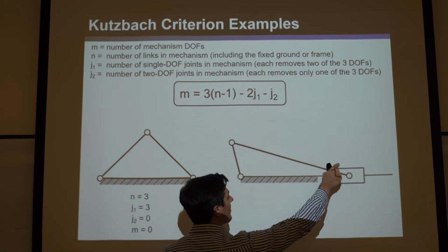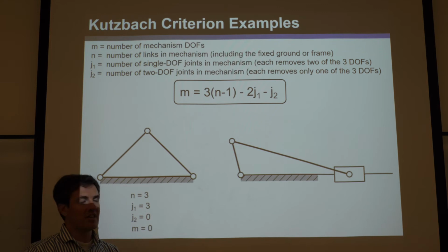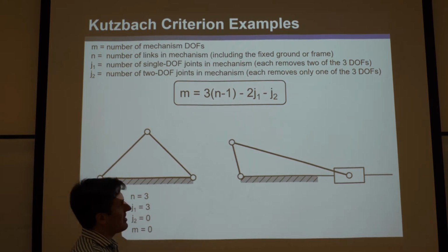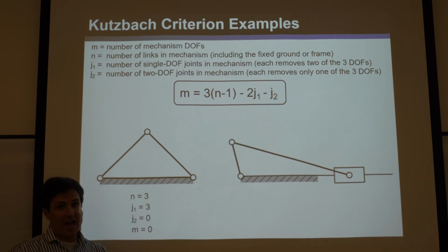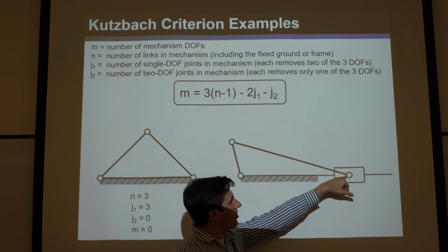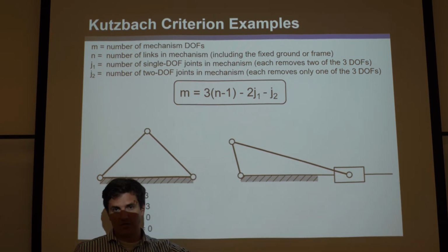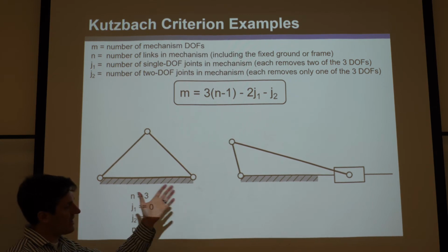You can clearly see here it is a closed kinematic chain, whereas the other diagram you couldn't see that as clearly. And yes, it does move, and it has a mobility. So it's a mechanism. And is it a linkage? Indeed it is, because it consists of all lower pair joints, okay? Lower pairs, because they're all surface-to-surface contact, okay? So it's a linkage, okay?